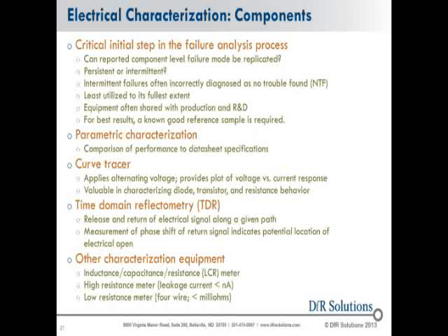There's also time domain reflectometry, where you inject a pulse into a device and then monitor what it does on the other end, or if it gives you some kind of bounce back signal. This is again where you need a known good device for comparison purposes, so you can spot any abnormalities or differences from the known good device, and then decide you need to focus further here.